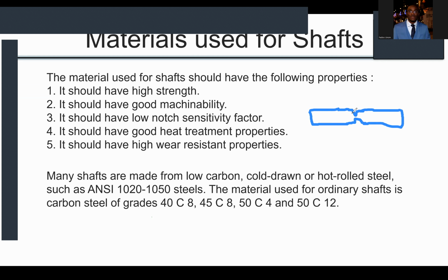And with notches, there's a lot of stress concentration around the notch. Okay? So when we talk about notch sensitivity, we are saying that material should not be very sensitive to notches. So if there is a notch and it accumulates stress and easily causes the material to fracture, to fail, then the sensitivity is high. All right.